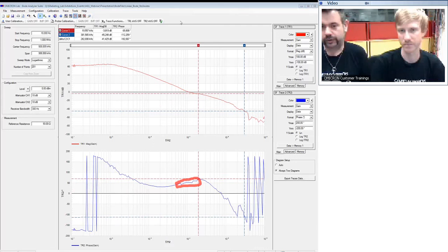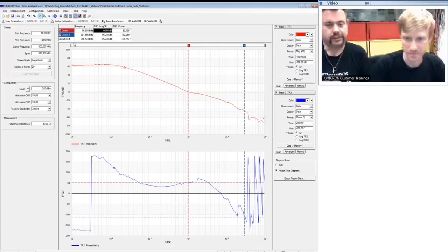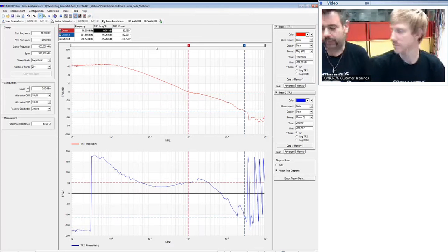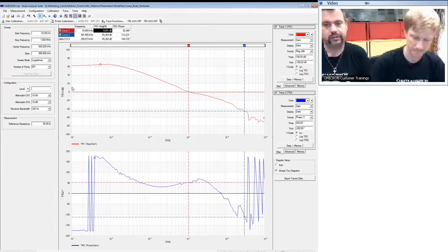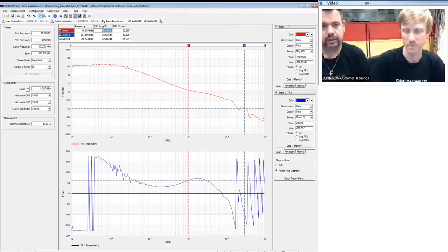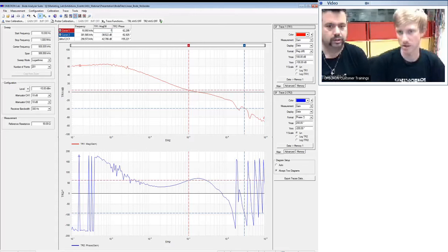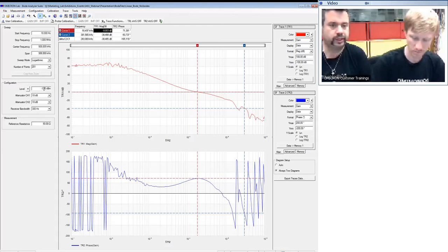And so the first thing is, it's always important to measure with the correct injection level. So what I do is, when I start to analyze a circuit, I start to reduce the injection level, and I reduce until the pass-through point is no longer changing. So let's start. We are at 0 dBm, put -10, and we have a look. Okay, it has changed. I enter 0 dB again to move the cursor to the crossover point. It's now 18.5 kilohertz. And I reduce the level further. Yeah, now we go to -20, let's say.